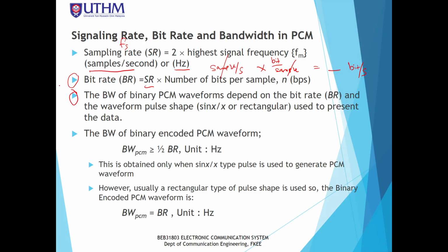What about the bandwidth? So the bandwidth of binary PCM depends on the bit rate and the waveform pulse shape, sinc or rectangular pulses used to represent the data.